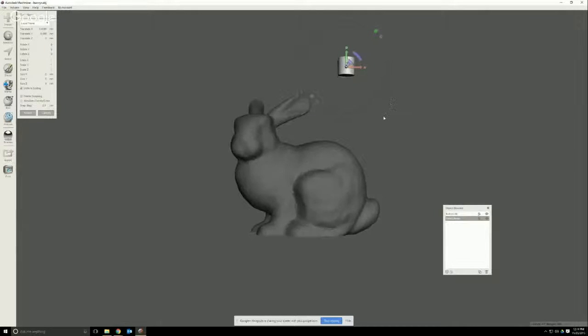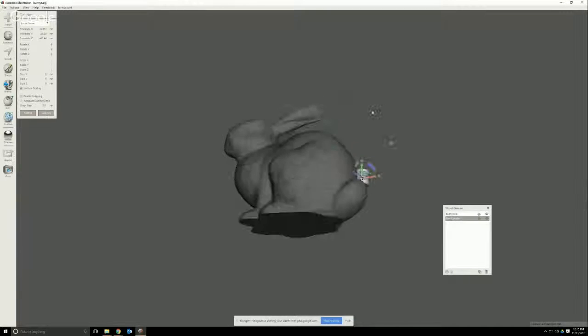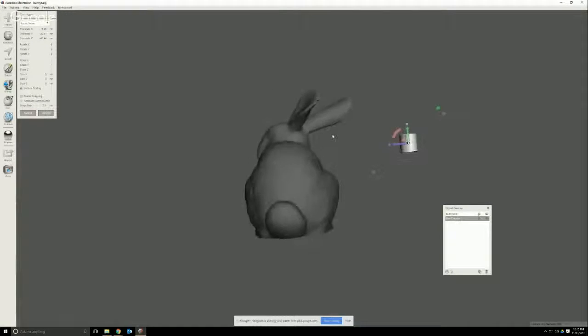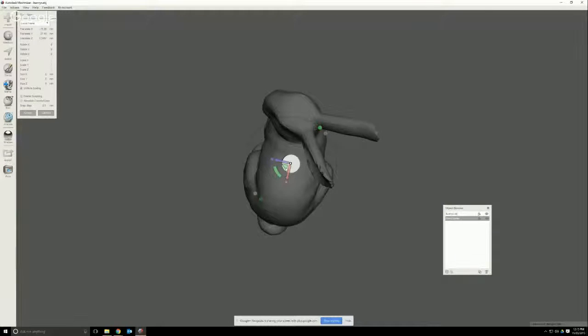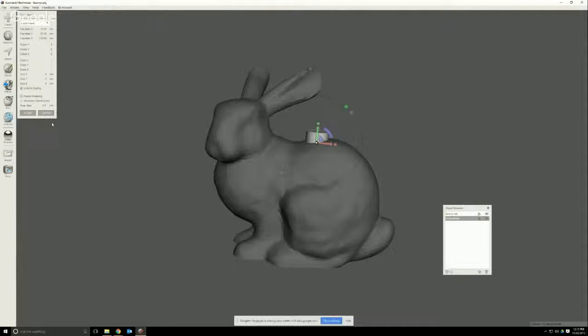If you want to align things in 3D space, let me kind of show you what this looks like. You can align it down here, and you say, okay, it's cutting out of the bunny, but then you look to the side and it's nowhere near the bunny at all. So the great way to do this is to go from one angle, align it to where you want, like right there, and turn around 90 degrees and go, okay, now I'm going to align it right here. And then just for good measure, you can go on top and say, okay, I'm going to use this alignment and put it right there. And then click accept. That was hitting the T for transform.